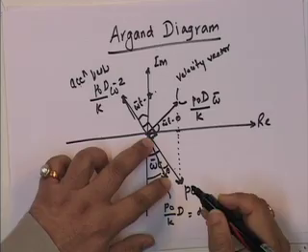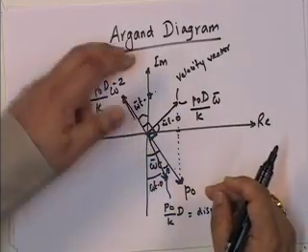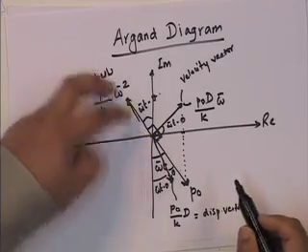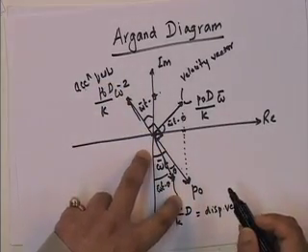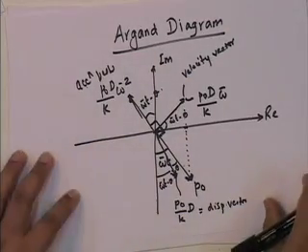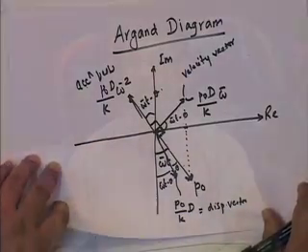We are going to do force equilibrium, Argand diagram, and it is going to be very interesting, because if you look at it, this is the displacement. The elastic force opposes the displacement, the inertial force will oppose the acceleration, and the damping force will oppose the velocity. These are interesting points, and we will look at this in the next lecture. Thank you very much.